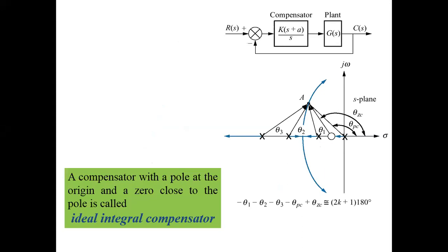While the first technique reduces the steady state error to zero, the compensator must be implemented with active networks such as amplifiers. The second technique, although it does not reduce the steady state error to zero, has the advantage that it can be implemented with a less expensive passive network that does not require additional power sources.